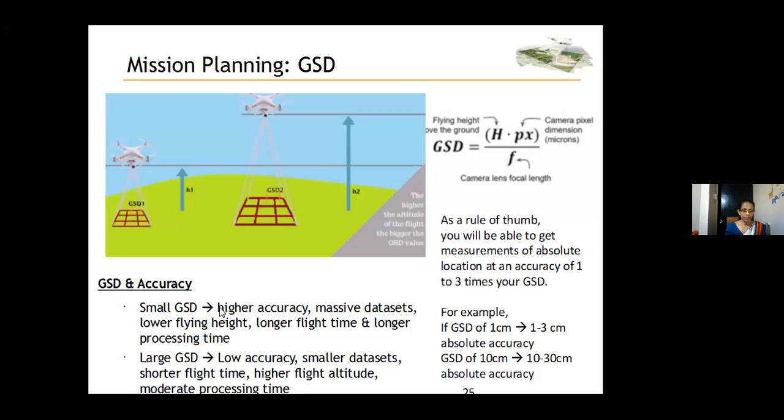If you think that you need global accuracy, GPS is most definitely needed for such surveys. Make sure you understand the project requirement well enough to know whether you need ground control points or not, because using ground control points will increase time spent on site and during processing. It also increases your cost.